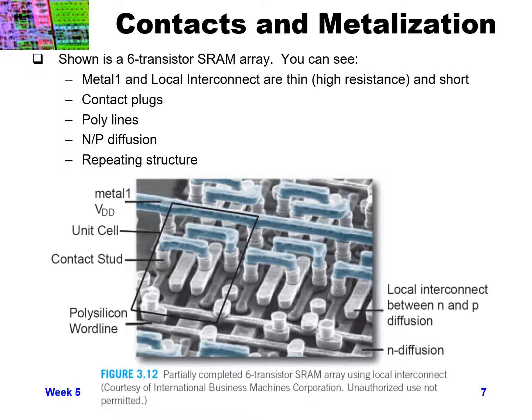and then there's round plugs basically between that blue layer and then the layer that's going more vertically. Between the blue layer and the plugs, there's a sort of whitish grayish layer that's going more vertically, and that's what's called local interconnect between the N and P diffusion.